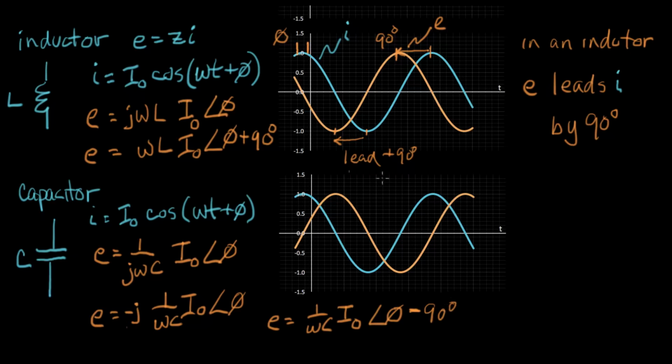So here's our original current here. Let me label that. Here's I. And now we have our voltage, E, looks like this. Here's E. And what we see, let me go out here and measure it, here we have a phase lag. We're pointing to the right of 90 degrees. And that we call a lag. We can summarize that.